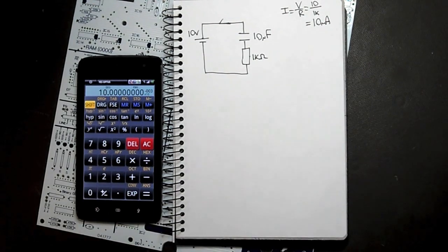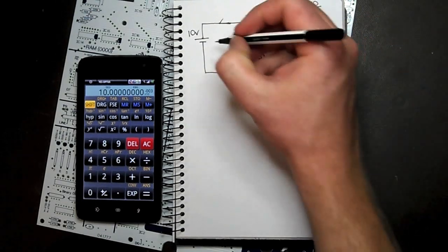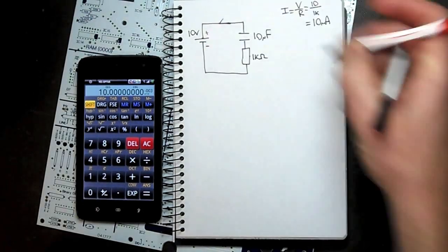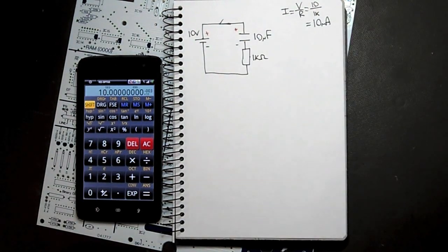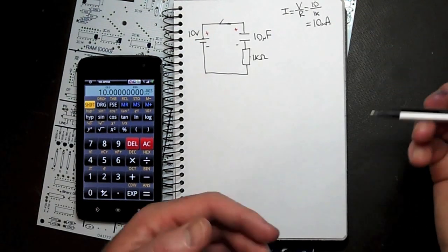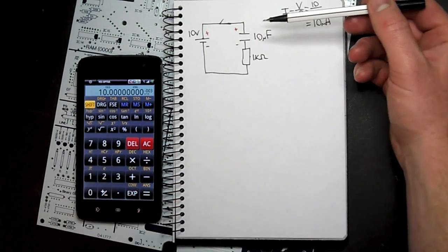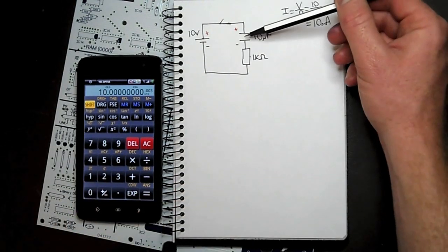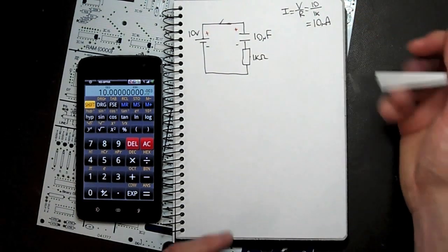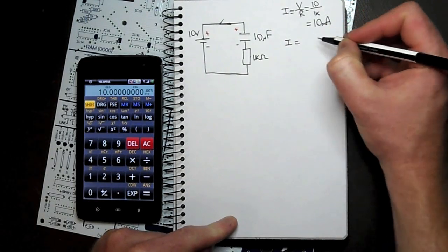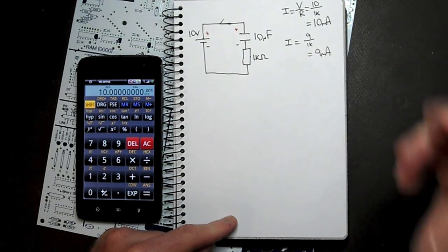Now, as I was saying before, as time goes on, the capacitor charges. We've got negative here, positive here. The capacitor will actually be charging up the same, negative, positive. So let's say after a certain period of time, this now has a charge on it and a potential difference of 1 volt. If this now has 1 volt, we've got 10 total, that leaves 9 for the resistor. So how much current have we got now? Well, it'll be 9 milliamps.